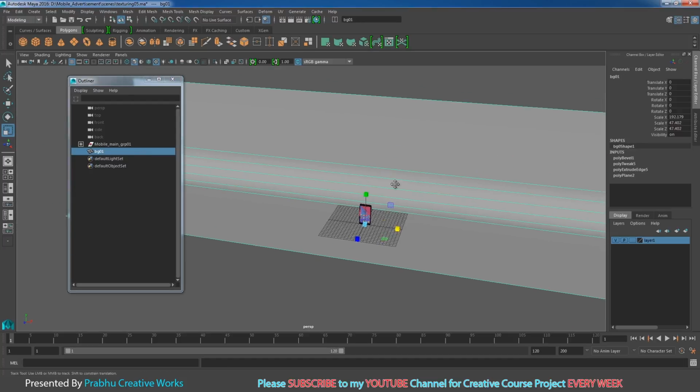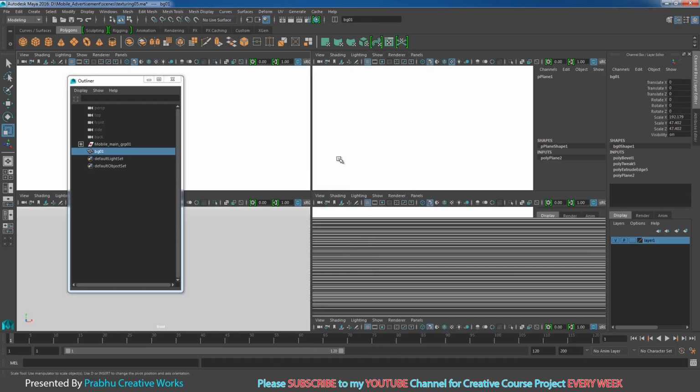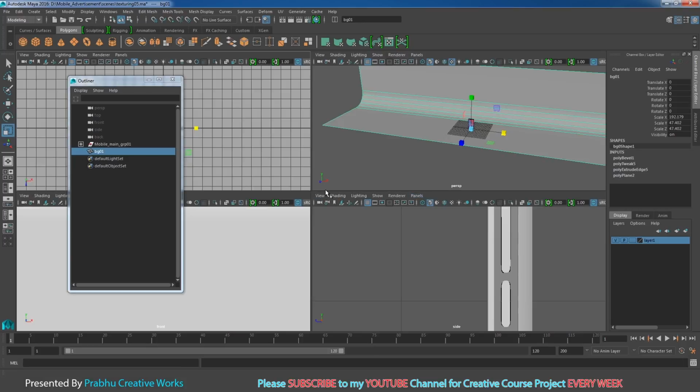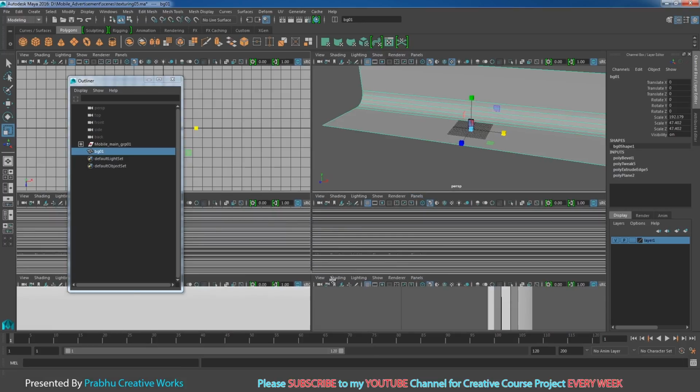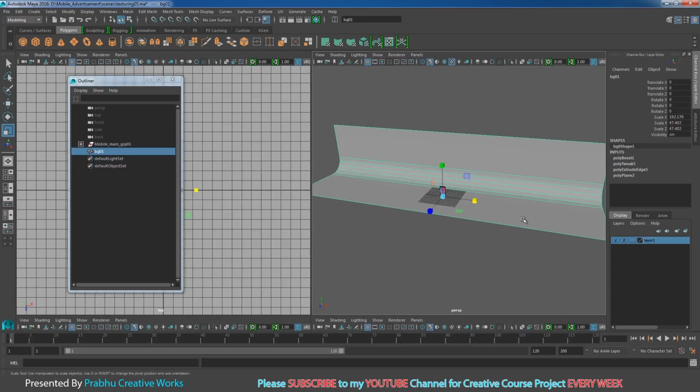Now before we start lighting, you want to set the camera view. So press spacebar on your keyboard. That means you get 4 views. I will click and drag over here. That means you get only 2 views. Here I want to set a perspective view. Here I want to set this as a camera view.